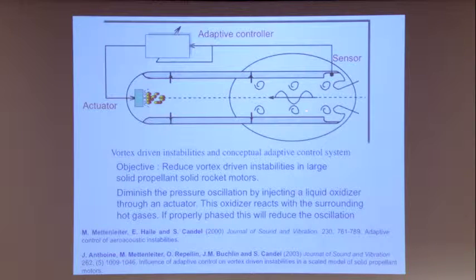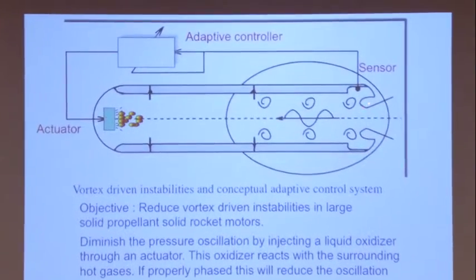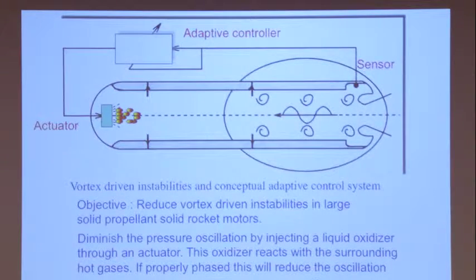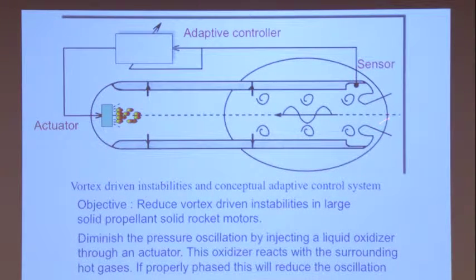So you have vorticity which is shed from the baffles, and this vorticity hits the nozzle, and pressure waves are returned by this collision of vorticity with the nozzle, and this produces a pressure field here, and if the pressure field corresponds to one of the modes of this system, you can synchronize the shedding of the vorticity, and so this system can become synchronized.